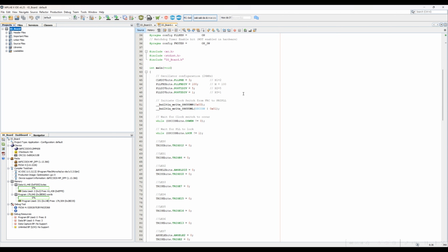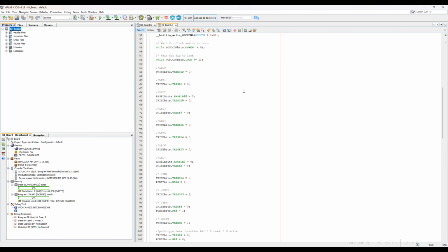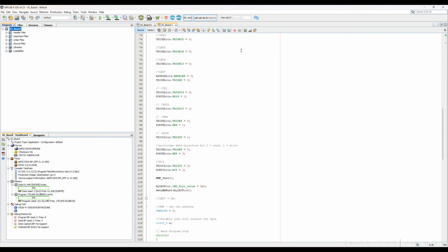I added some more comments, and then I added the control lines for the SRAM. So we have the chip enable for it, and the busy signal. When there's two writes at the same time, this busy signal goes low. And then they have a semaphore pin.